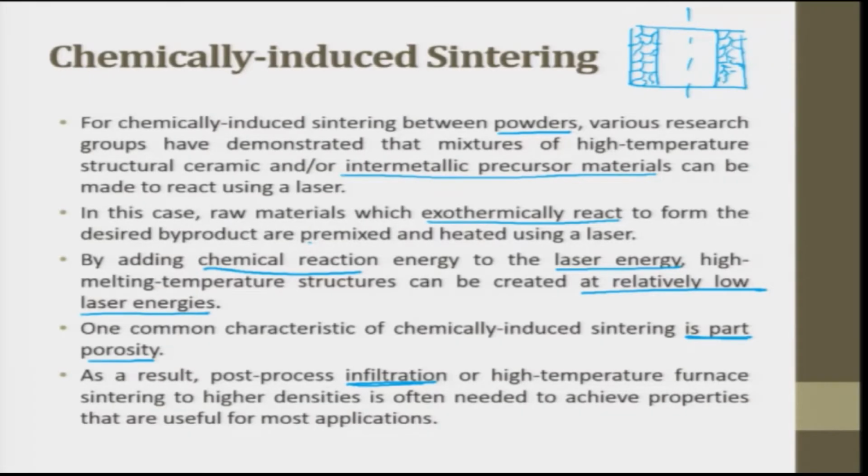So now what you do is, either you post process the bush once again and try to consolidate it, or we try to infiltrate. For infiltration, either we create a vacuum pressure here and allow the liquid from outside to enter inside, or you pressurize at very high pressures and push the liquid in between the pores. So that process is called infiltration.